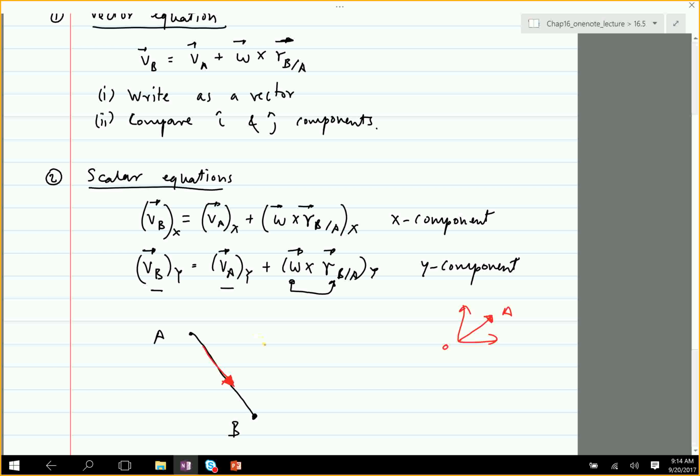So would you write this as B with respect to A or A? Well, this is B with respect to A, this is A with respect to B. So you'll write it clearly like the first one. You normally write this as RA. You normally do not write RA with respect to O, because O is the origin. So if you forget whether it's A with respect to B or B with respect to A, draw a figure like this with the origin, and you always write it as RA. Wherever the vector points to is always the first thing, so you can remember it from that.